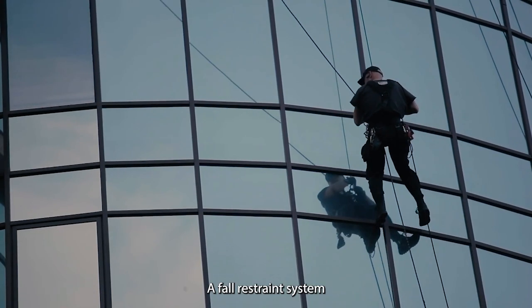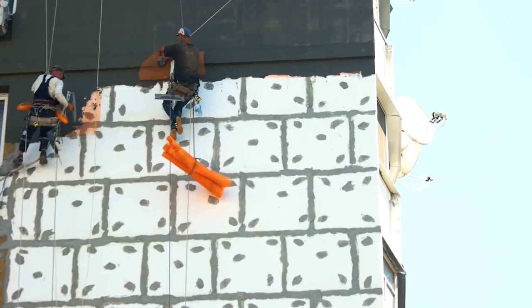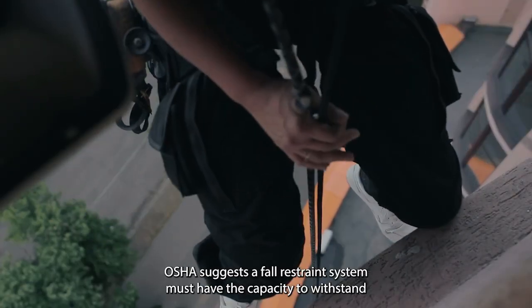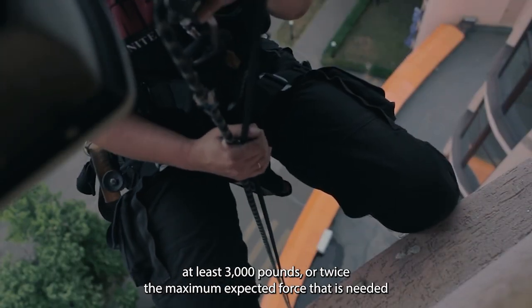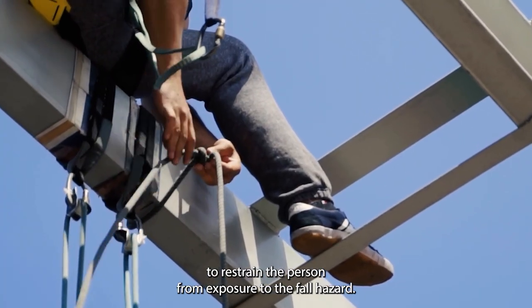A fall restraint system tethers a worker in a manner that will not allow a fall of any distance. OSHA suggests a fall restraint system must have the capacity to withstand at least 3,000 pounds or twice the maximum expected force that is needed to restrain the person from exposure to the fall hazard.